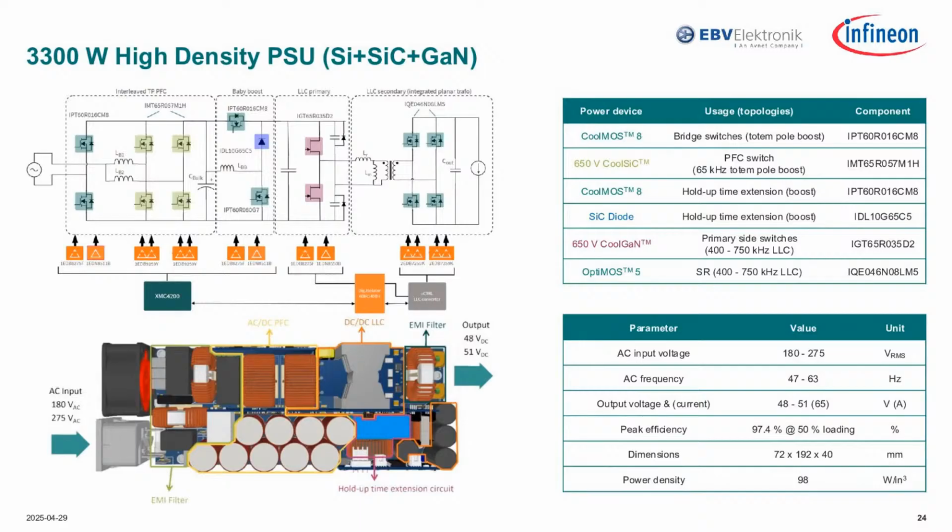First of all, wide bandgap provides a very robust body diode, which this topology is looking for, particularly for CCM totem pole PFC. Also, regarding the switching frequency, as mentioned by our colleague Edward, the lowest switching losses are with gallium nitride.